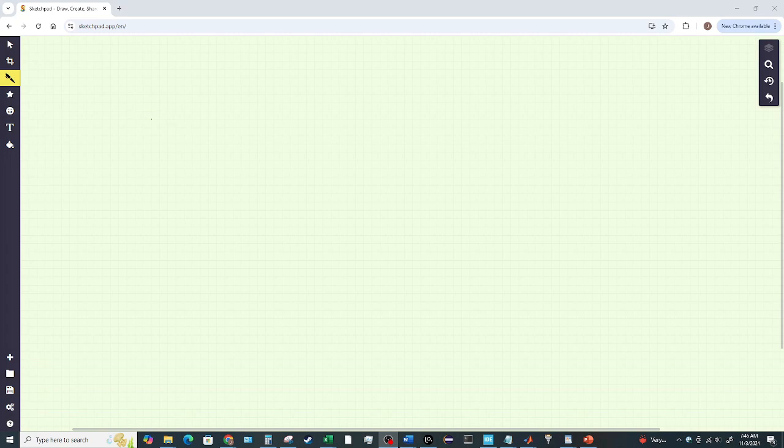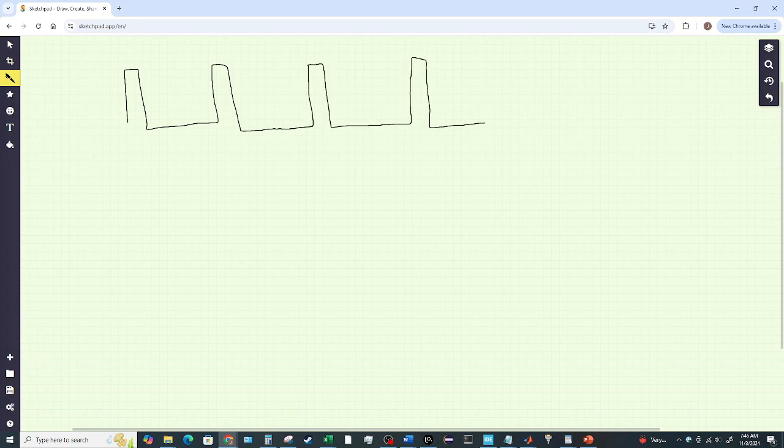So in our PWM waveform, we're going to have pulses coming in. The duty cycle doesn't really matter for the stepper motor as long as these pulses are wide enough for the driver to accept them. We've got a couple of different things to think about here. What characteristics do we have? We have the overall pulse period, okay, so that's the period.